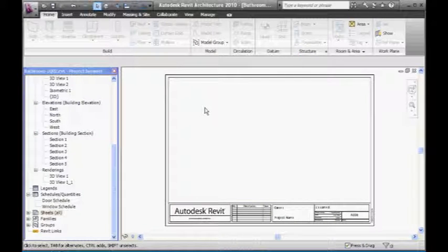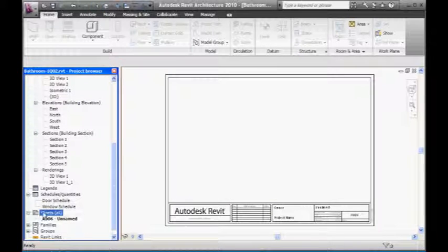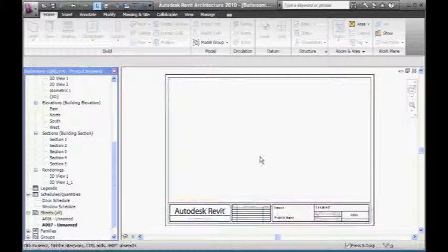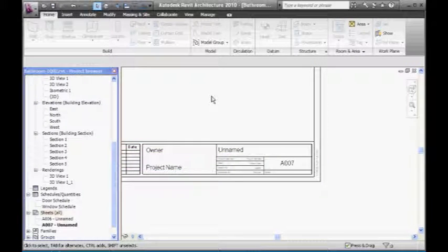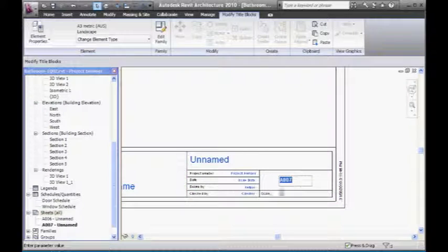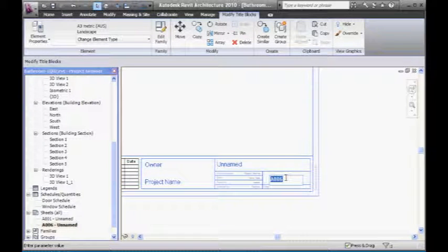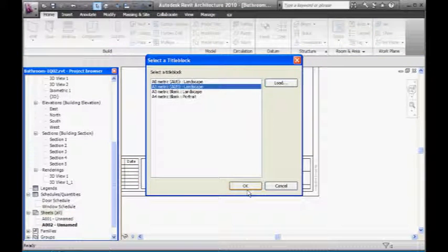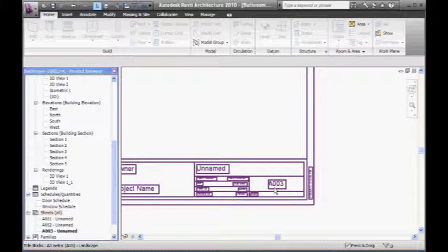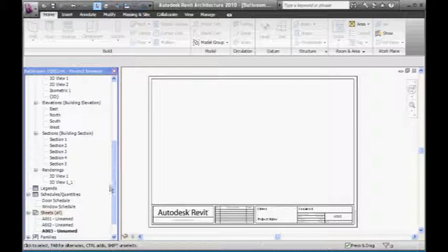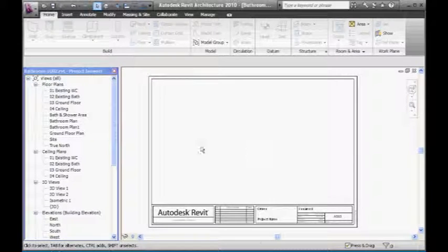Okay, so clicking OK there makes a new sheet for me, and it's not a problem if you want to make a couple at the beginning, because things will definitely spread out over a few sheets. So I might change my first drawing number there to A001 and my second drawing number to A002. And now when I make new sheets, at least it'll be able to pick up from the last drawing number and number them consecutively from there. So I've got a few sheets there. I'll probably need to add more, but that's good enough as a starting point.